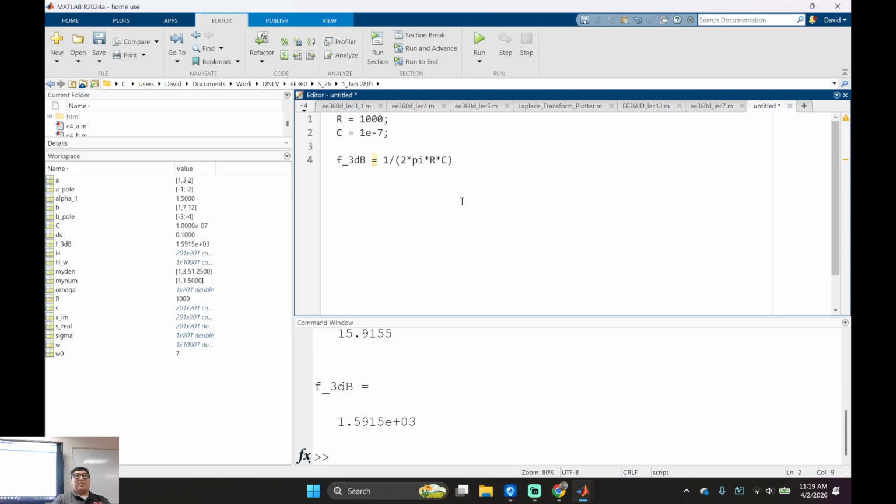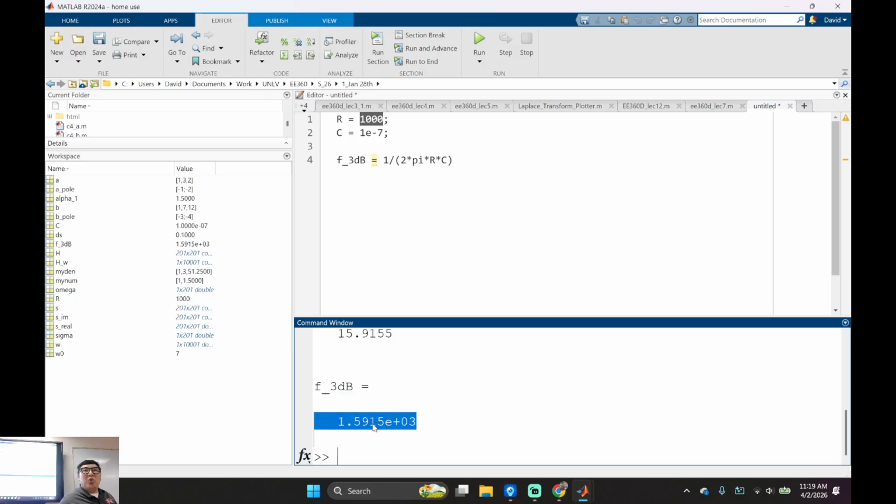Okay, so I'm going to do an experiment right now. 1K resistor, right? And 100 nano or 0.1 micro. Okay? So where's my 1K resistor? And then my 100 nanofarad. So we're predicting the circuit, right? We should start seeing a dip at 1.59K, right?